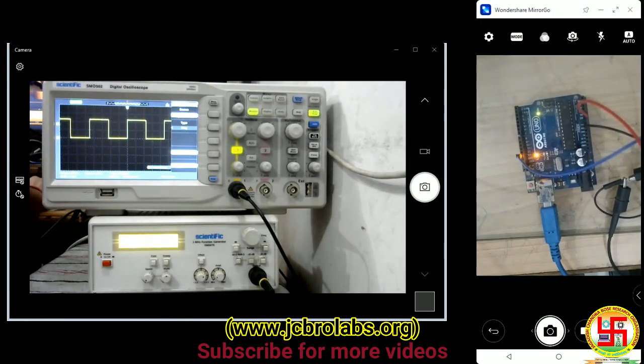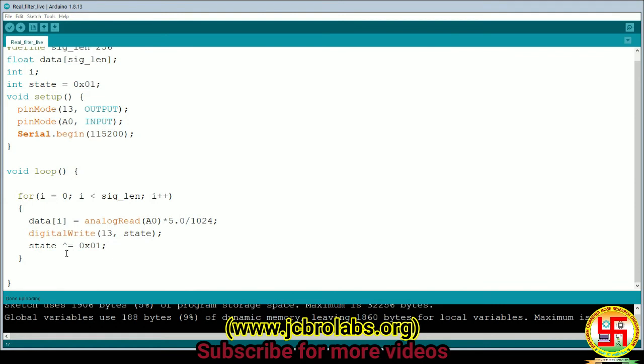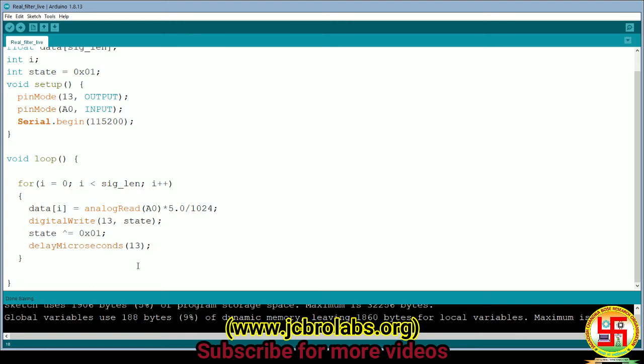So we will try to put some delay so that we can get a toggling frequency of 4 kilohertz, and then we can get the entire sampling rate around 8 kilohertz. Okay, so we will provide a delay in microseconds. I tried it earlier, and if I provide a delay of 13 microseconds, then it will be very similar to the 8 kilohertz sampling frequency. Okay, and that's good.